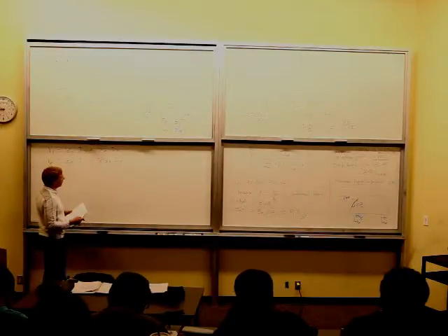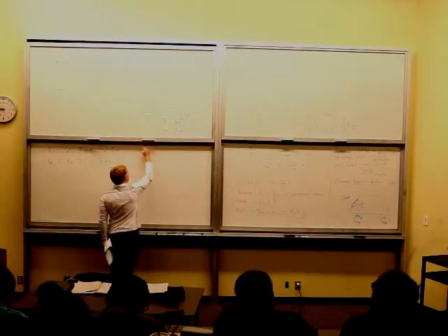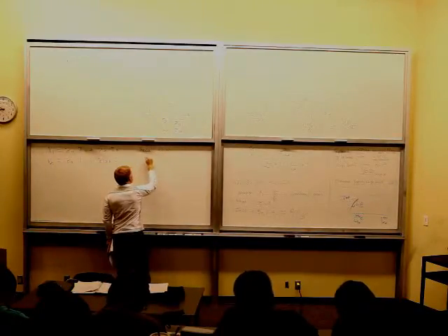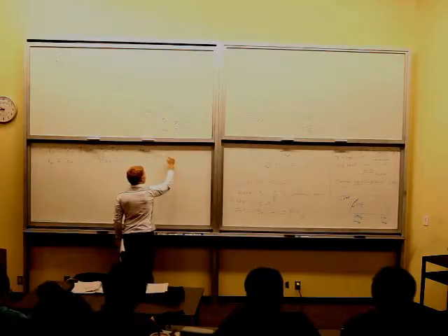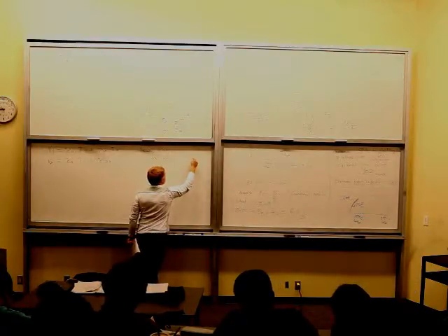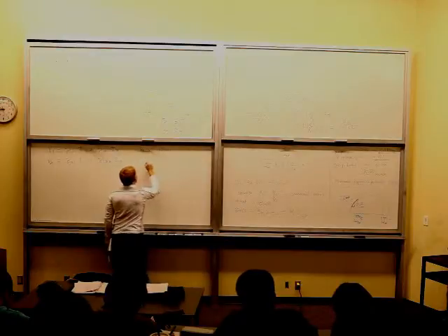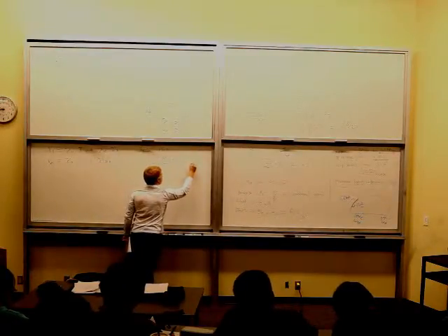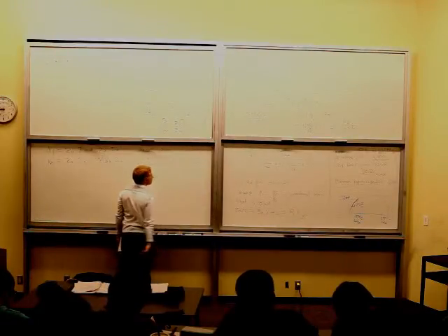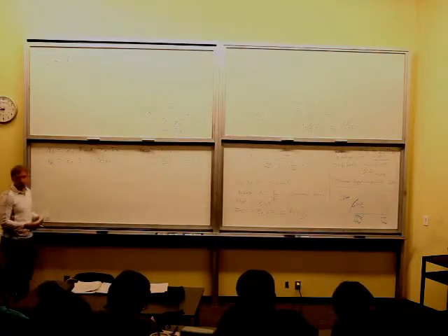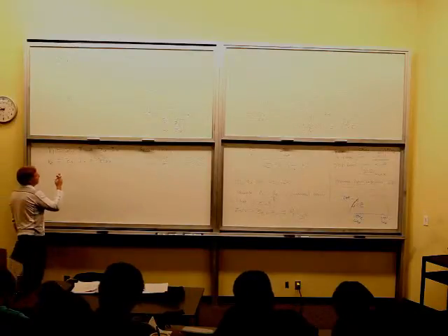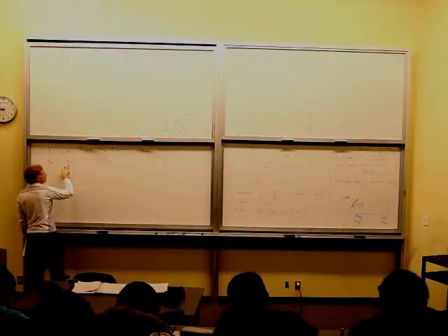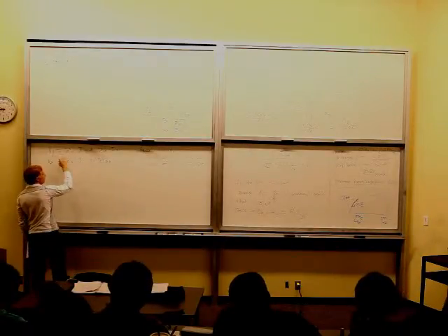So recall that to shut off a current, so I'll say shut off I, we must open circuit. Shut off V, we must short circuit. Alright, so in order to find these parameters, if you remember, it's easiest if you just shut off one half of the equations here. So we're going to find Z11, then we're going to find Z21, because we're going to reuse the information for Z11.